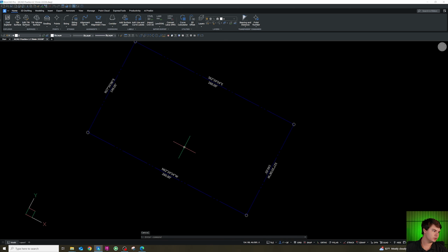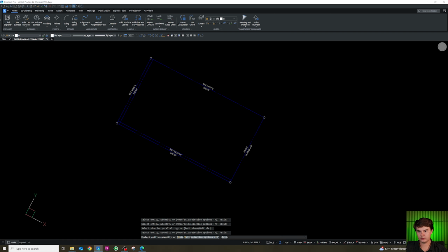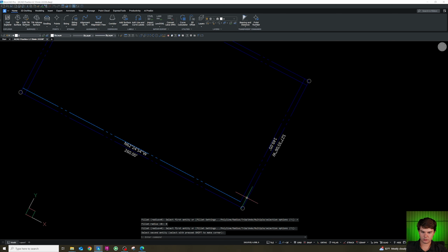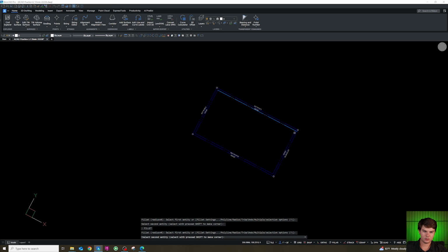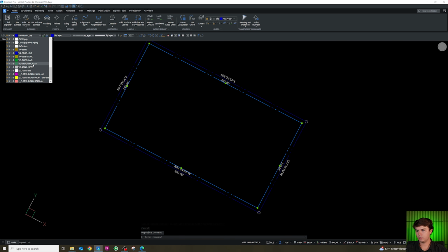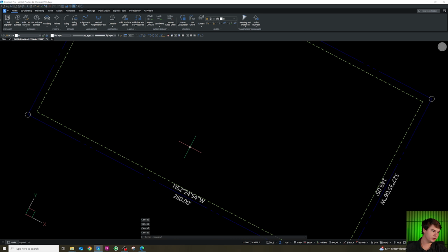And now this project does not have landscape strips or building setback lines drawn in. We can go ahead and just put 5 feet for landscape strips around. This is just a guess. That's this, and then we will put these on the landscape strip layer.